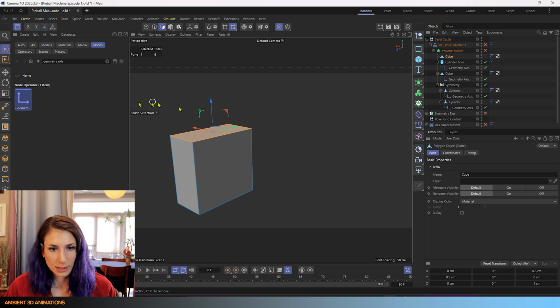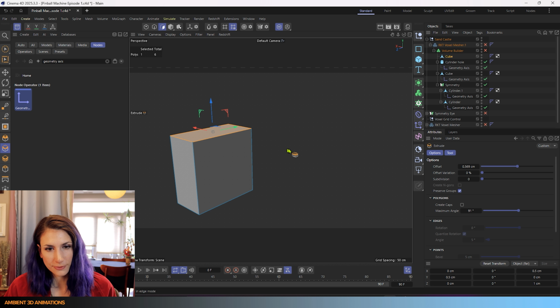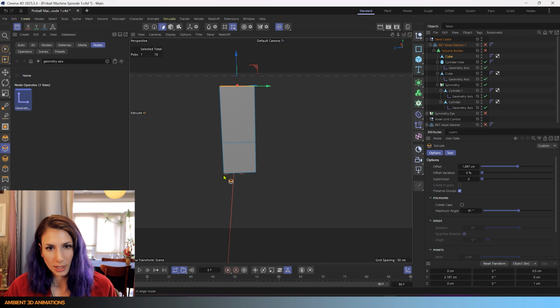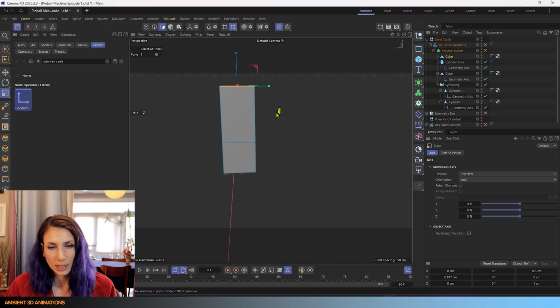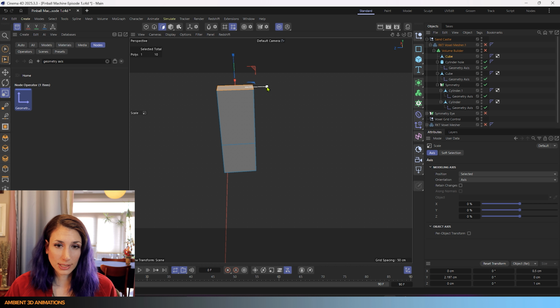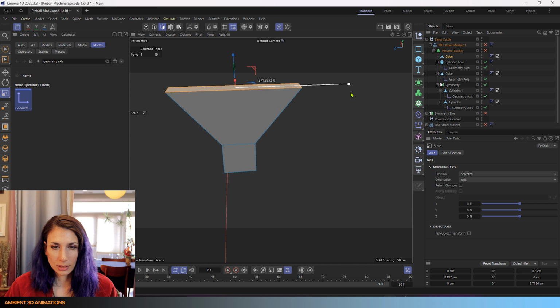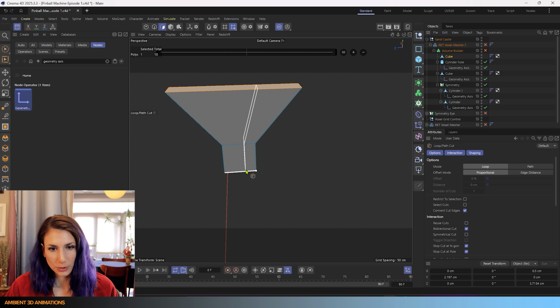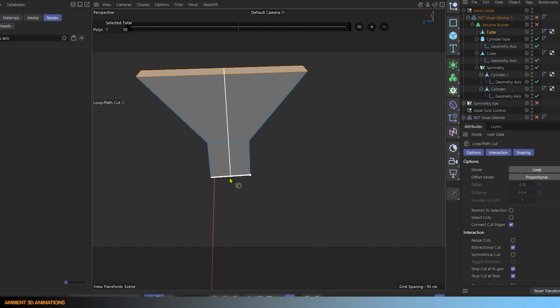I'm going to grab this top polygon with the selection brush, use MT for extrude, click and drag, and now this is moving up, which is great. Now we can use T again to extrude, or not extrude, scale this direction. So I'm going to click on this little green guy here and do that. Now we're going to need ML to add in some loops here, edge loops.